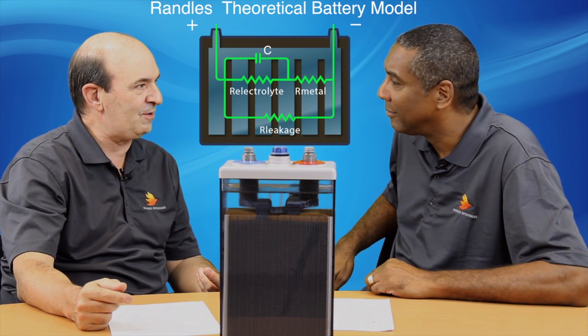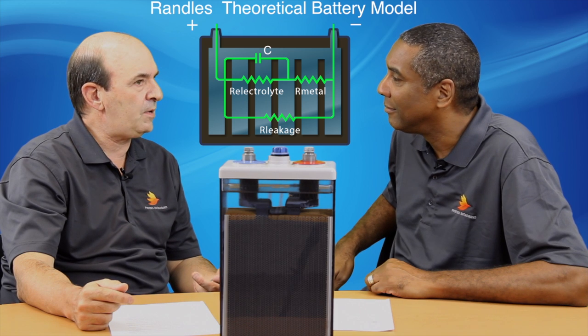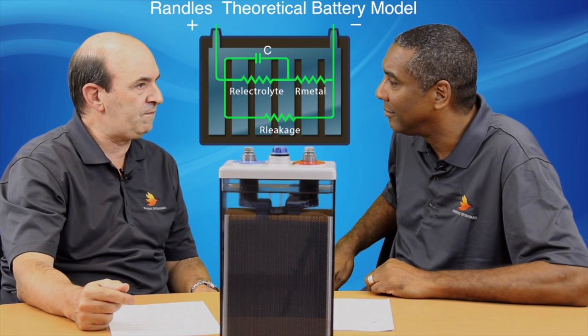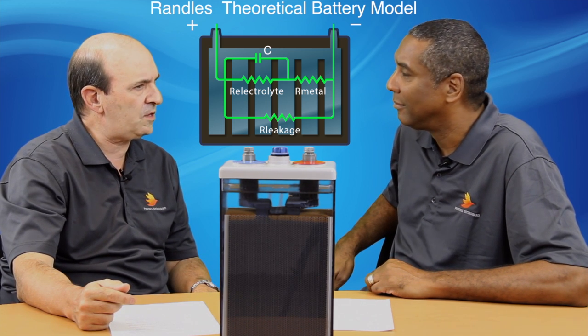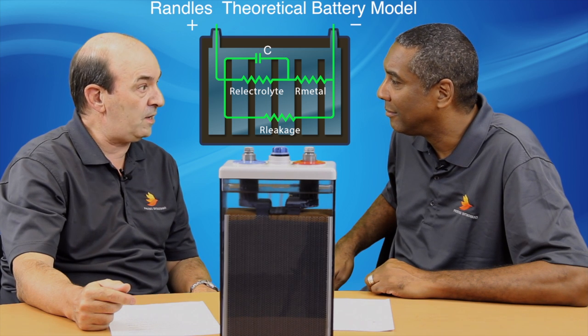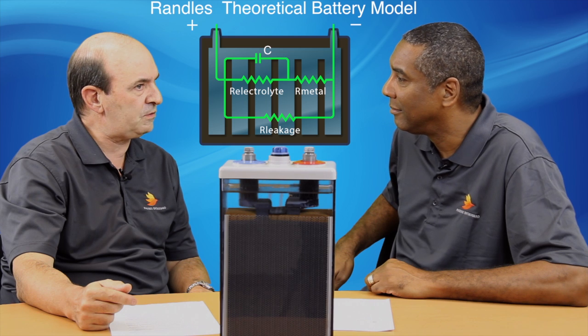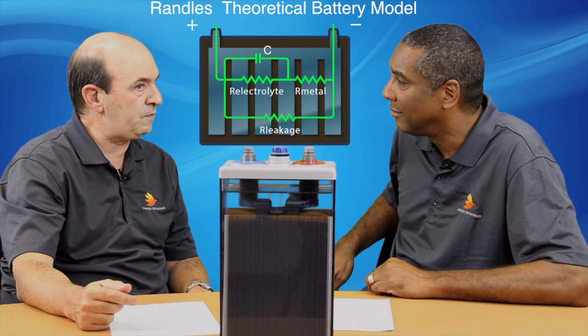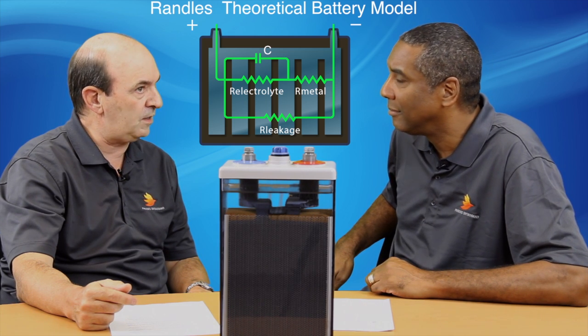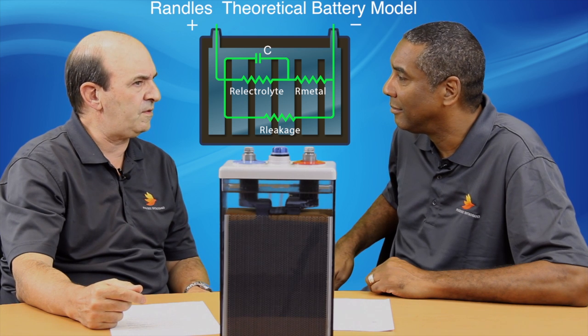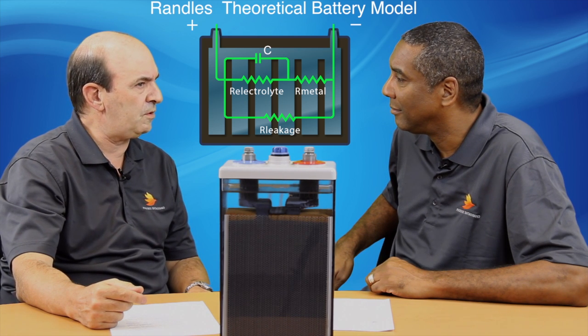Okay, so what are these non-ideal components and how do they affect the battery's life or performance? Paul, a good way to describe this is to use the well-known Randles theoretical model of a battery cell. As we can see here, a cell can be thought of as a perfect voltage source in combination with several resistors that limit the amount of current the cell can supply. The cell voltage is determined by the electrochemical reaction between the metals used for the battery plates and the liquid electrolyte. Of course, it's a bit more complex than this, but this very basic model will serve to help us